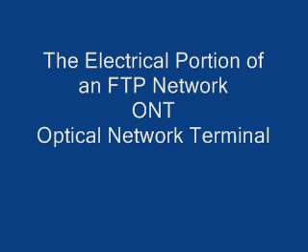Once on private property, the signal typically travels the final distance to the end user's equipment using an electrical format. A device called an optical network unit converts the optical signal into an electrical signal. Optical terminals require electrical power for their operations, so some providers connect them to backup batteries in case of power outages. Optical network units use thin film filter technology to convert between optical and electrical signals. For fiber to the home and businesses, it is common for the building's existing phone systems, local area networks, and cable TV systems to connect directly to the ONT.